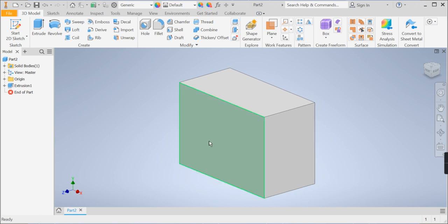Now what we're going to look at now is cutting out our shapes. So because we have to cut out a shape, we then need to start off again with a 2D sketch. So we then need to choose what surface we want to sketch onto. So I'm going to start my 2D sketch and then click the surface I want to cut into or subtract into.